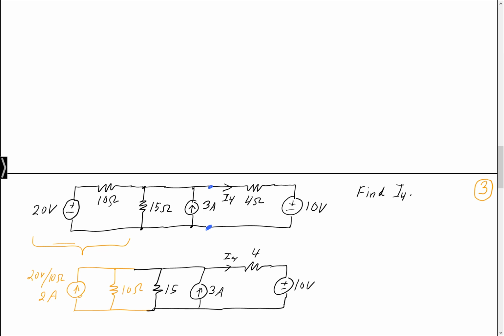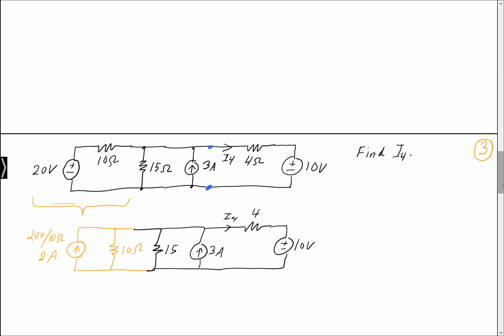Simple enough. Now again, and I said "again" one more time, I just can't get rid of it, we see a situation like what we saw before. We see two current sources in parallel and two resistors in parallel, because those four elements I just mentioned are between these two terminals. So we have 2 amps plus 3 amps.